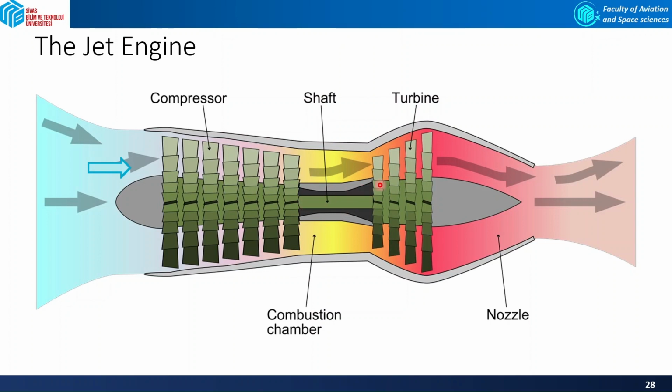After the turbine, the air still has lots of energy, and it can expand more through the nozzle that you see in here, and then it will expand up to the jet velocity and leaves the engine. So the jet velocity mainly depends on the energy that is put into the gas with the fuel and the pressure of the gas inside the engine.